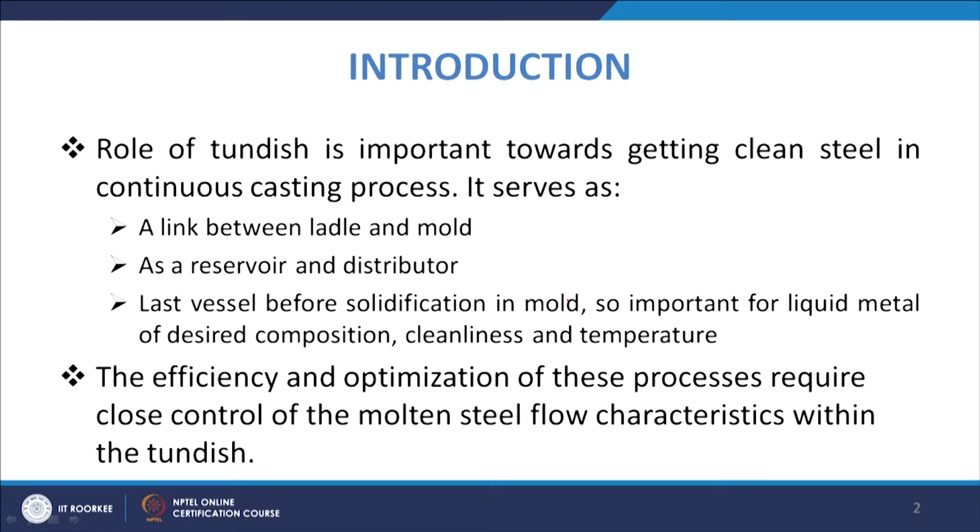You need to understand the flow, in what way the flow is there inside the tundish, the metal which is coming from the ladle, how it is flowing out of the tundish. So, where it is striking the wall, or whether it is going into all the corners of the tundish, whether any region of the tundish is there where the metal has gone and it is a dead region which is getting cold or so.